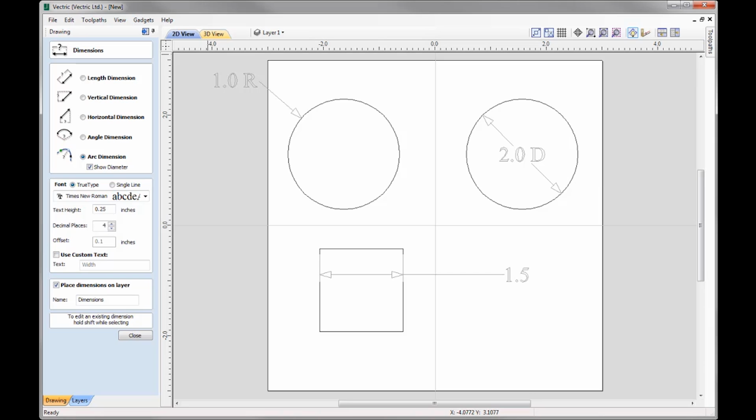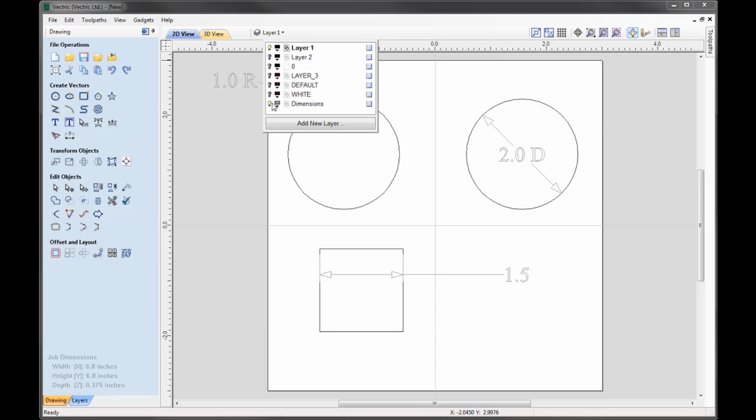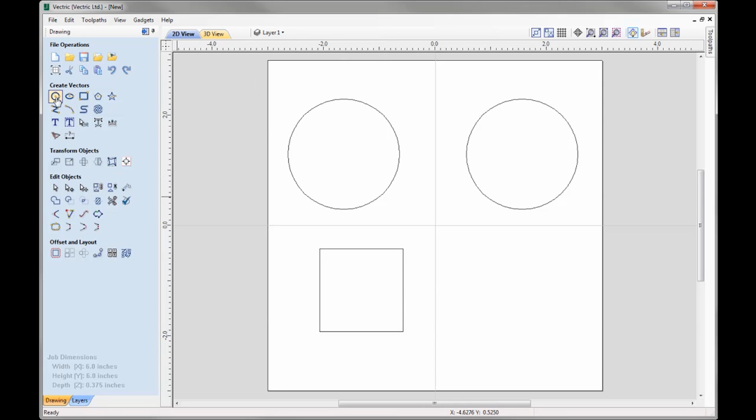Another enhancement we've made, which you saw briefly here, is the ability to edit shapes whilst in the relevant shapes form. So you saw that I held down Shift while selecting a dimension in order for us to edit that. Let's have a look at some of the other shapes that enable us to edit existing shapes. So we'll close that down, I'm going to go to the Layers tab to switch off the Dimensions layer, and then we're going to go into the Circle form.